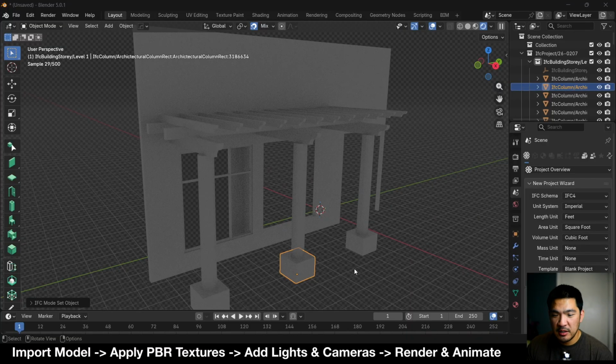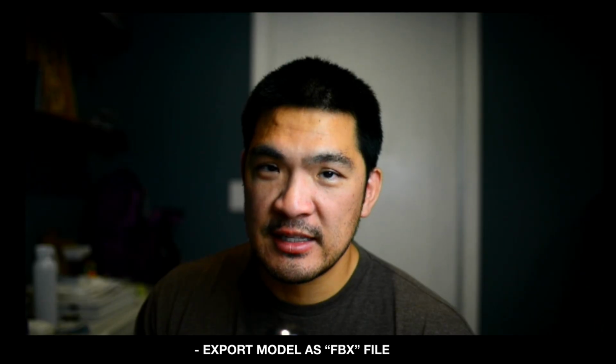But now you can apply PBR materials using the shader editor, set up lights and cameras, and render or animate your scene using the good old Blender tools. That's one way you can get a Revit model into Blender. Another way is to export your Revit model as an FBX file. Those are probably the easiest ways to do it.